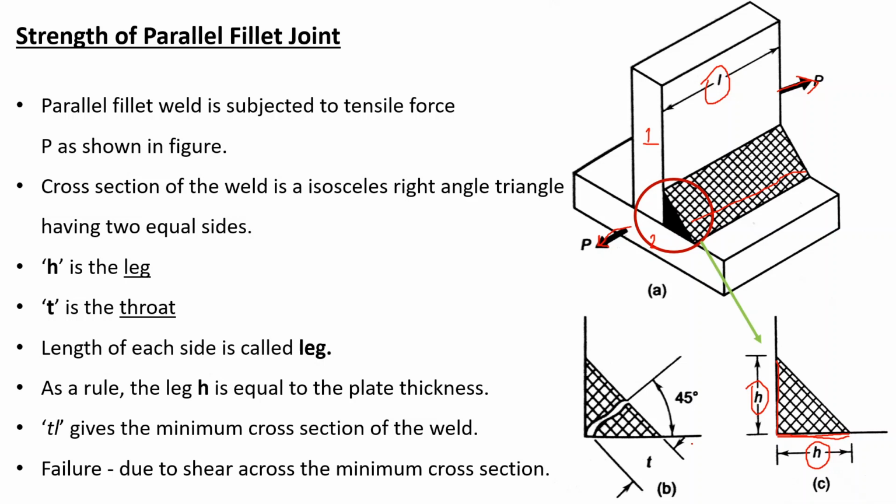So always keep in mind that the leg of the weld is taken equal to the thickness of the plate.